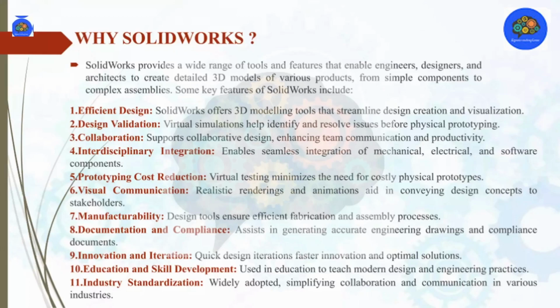The documentation and the compliance. Documentation means if we use another software as a CAE software to make the analysis, and we are using SolidWorks software for creating the CAD models, if we are going to transport that model from SolidWorks to any of the analysis softwares like ANSYS and HyperMesh, we are going to use some specific IGS format or else part file format and STEP file format. In those formats we can easily change that.